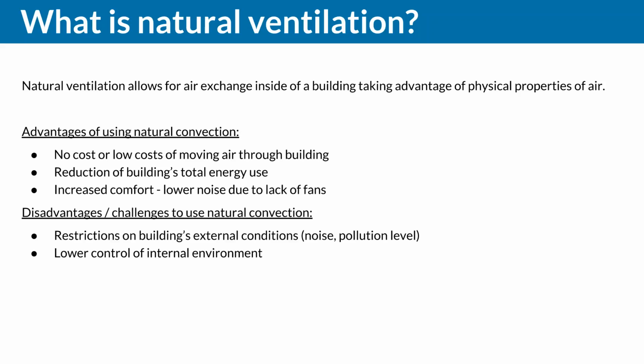And in practice, usually we're talking about two effects. One is what we call natural convection. If we have any heat sources inside the building, the air near these sources will heat up, and the density will drop, and therefore it will rise. This is an effect which you can see not only in buildings, it's also used for cooling electronic devices.